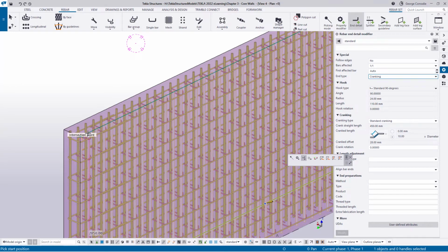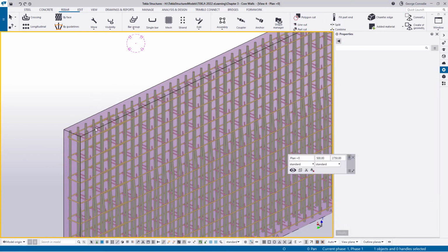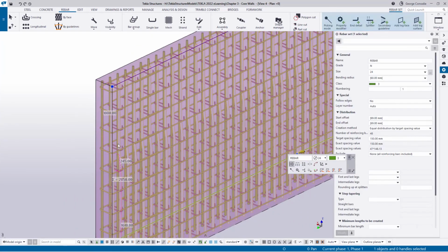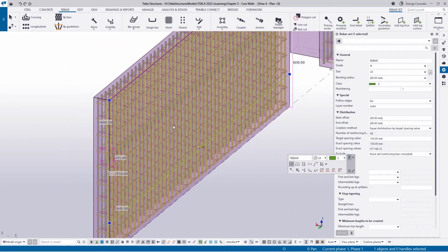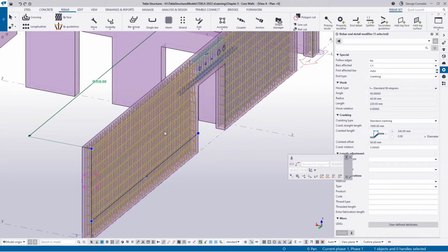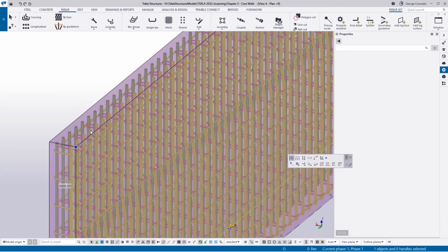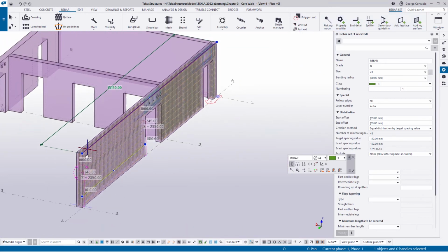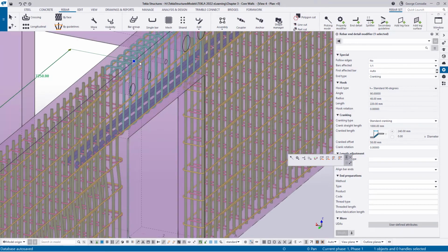And then what I'll do is I'll just hover over the edge of that panel, and now you can see what's happened is it's given us, if we look at this bar, a crank, but it's got the crank down below there. So what it's done is, if you click on that end modifier, and by the way, just before we do that, let me click on the bar again and hover over the end modifier. If I grab that arrow there and bring it back to this door opening, because that's the only place this one feeds to, is to this end.